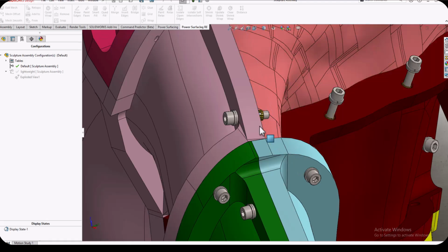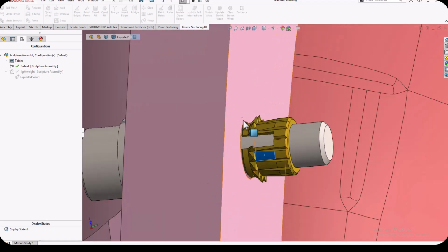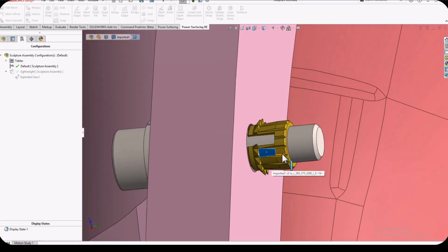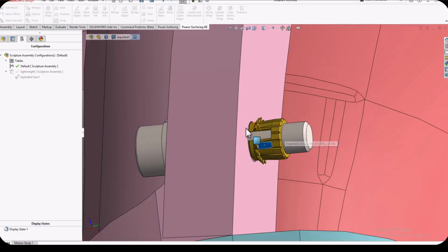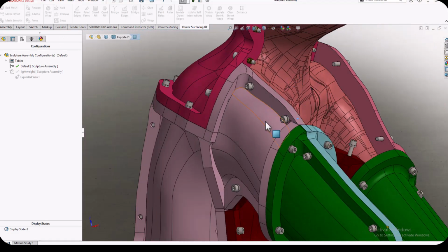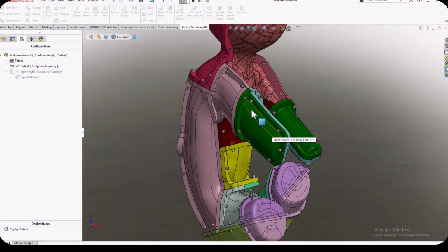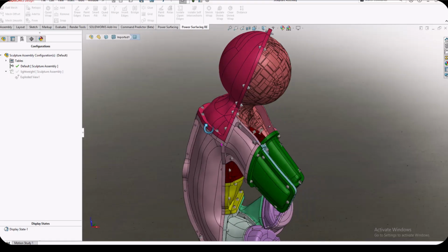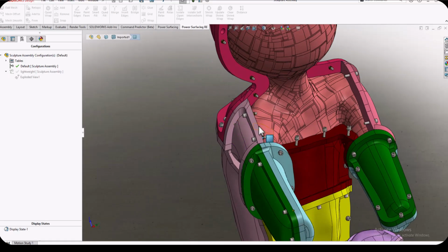For the threaded inserts, the installation process is straightforward. We simply heat the insert using a soldering iron and press it into the printed plastic. Once it cools down, it becomes permanently embedded inside the mold. There's one more important point I'd like to mention. The client wanted every mold section to be fully 3D printable. I recommended printing the molds using TPU filament instead of a rigid material.